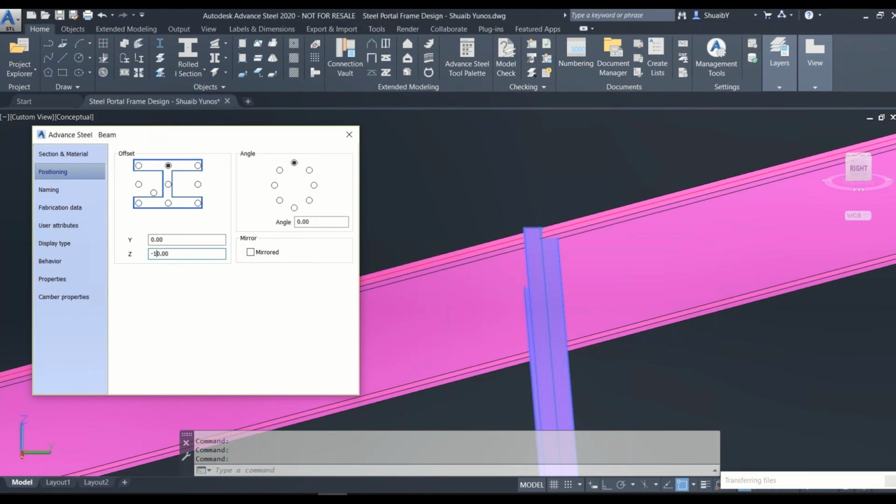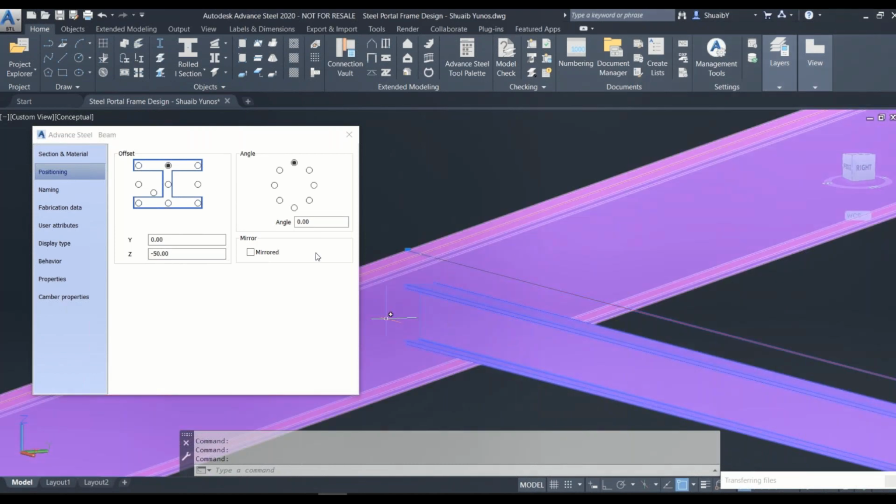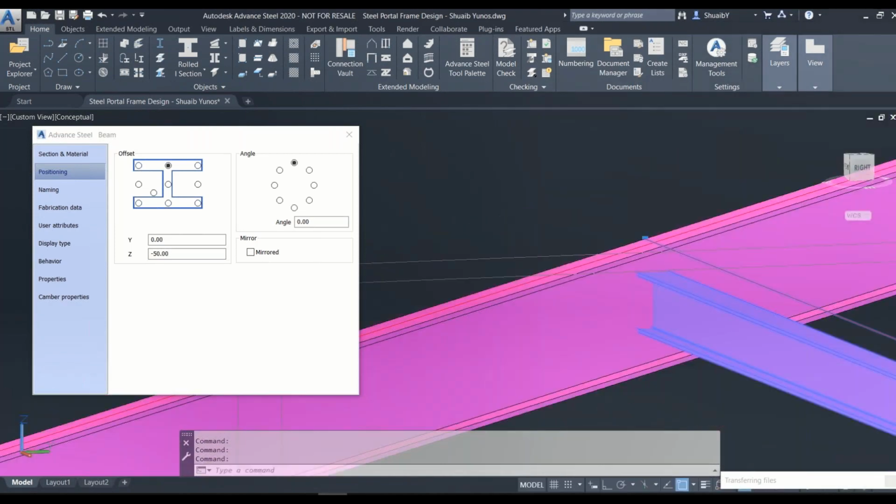we will be happy with. So you can actually see, because remember your IRB or your roof sheeting is going to go on the top, so you need a tolerance for that as well. So let's say maybe 50. Let's have a look. That looks okay in this model. So we've got the 50. And now you can see the angle is still not matching up.